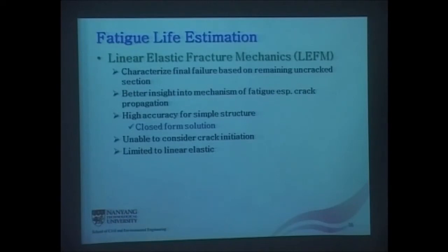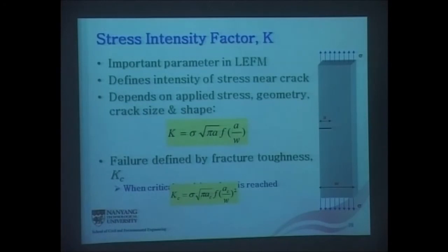So now we go on to the estimations using the linear elastic fracture mechanics. All right, based on remaining crack sections, we can provide better insight into the mechanism of cracks, especially crack propagations. And then the high accuracy is in closed form solutions. Okay, but it's unable to consider crack initiation. Right? It's limited to linear elastic. Yeah. Okay, these are very familiar to those who work on fatigue, the stress intensity factor K, and using this, same as what we have used for experimental and numerical.